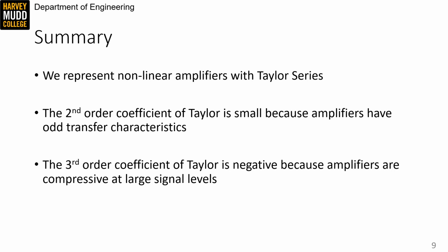So in summary, we represent nonlinear amplifiers using Taylor series. The second order coefficient of the Taylor series is small because amplifiers usually have odd transfer characteristics. And the third order coefficient of the Taylor series is usually negative because amplifiers are compressive at large signal levels.